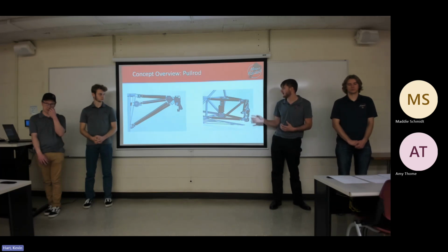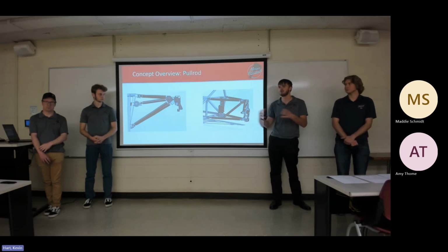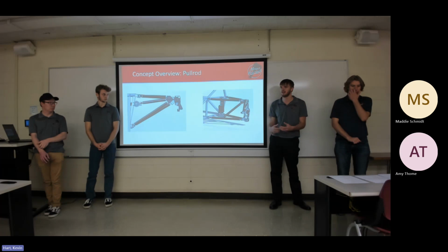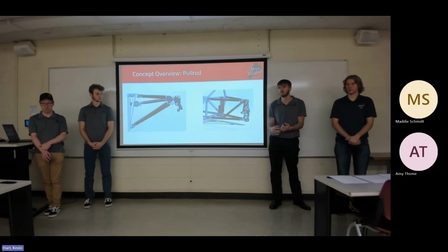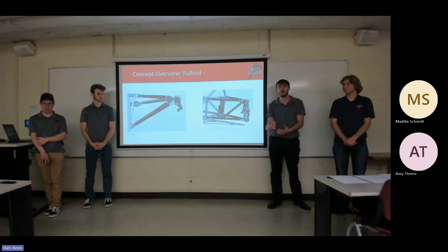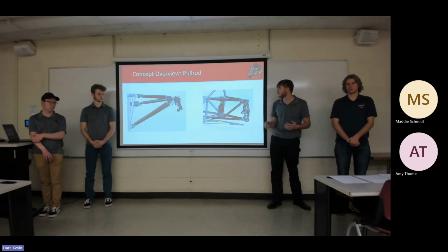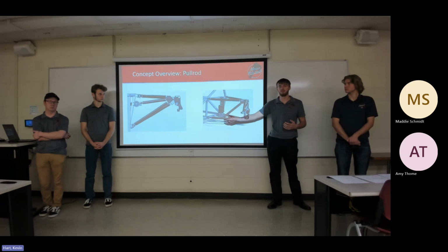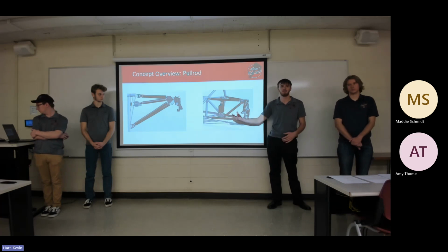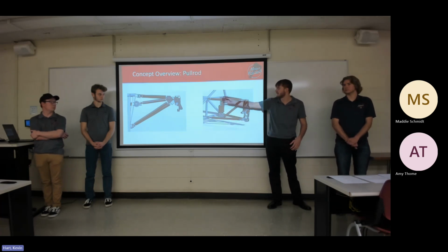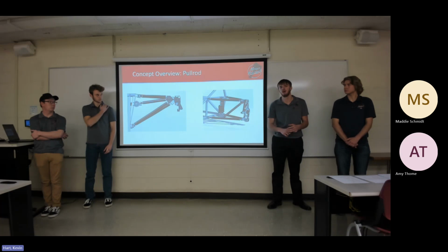The advantages of this design are that we're not only keeping everything outboard of the front of the car, we have things like electronics and bodywork that are looking to go up on top where a lot of the front shocks are mounting. So by being able to keep everything outside, we are able to allow those places more space to sit, along with being able to keep all our weight very low, the bell crank and shock being the primary heaviest parts of this assembly. By being able to keep them outboard on the low side of the car will give us the lowest center of gravity.